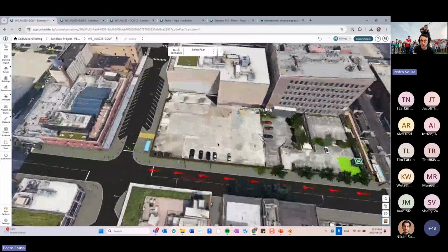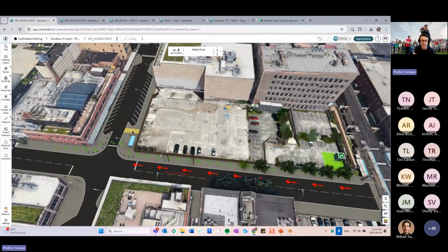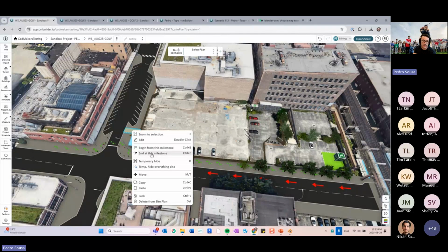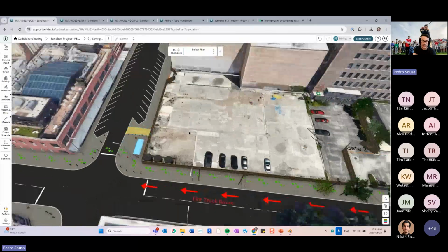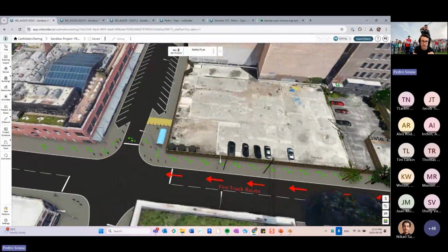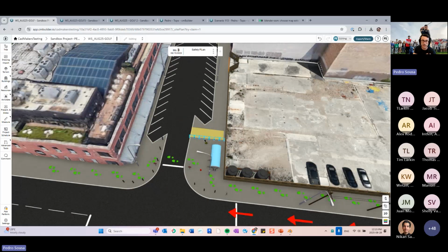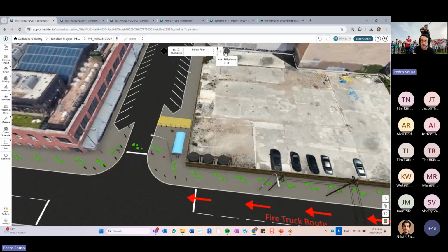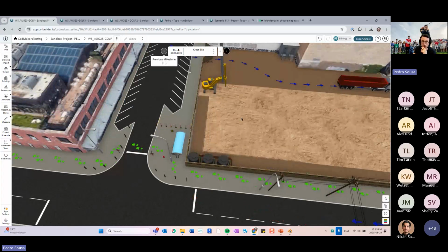So these annotation elements, again, we can always just go in and say that I want to see these objects only at this milestone. So if I'm active in this milestone and I'm placing the objects, by default, that's going to be the first date that they're going to show up. But it's always important, if you want them to be visible only here, to put the end dates to be at that milestone. Okay.